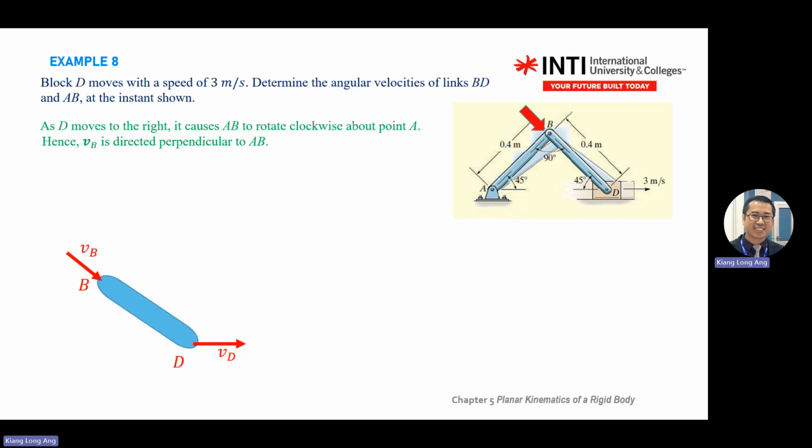Then D, again, use your ruler. Put to D, put to B, you should be able to find the intersection point, right? So B is here, pull here 90 degrees, D, pull 90 degrees, right, IC. Then the arrow always points from IC to the point, right? RB stroke IC, RD stroke IC.